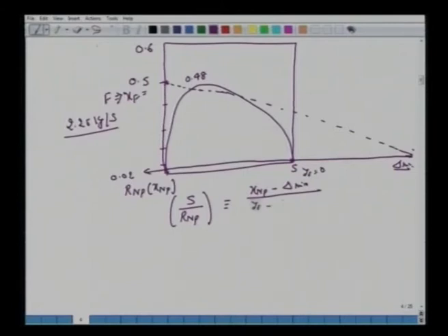That means we should make use of other quantities, let's say F here. Now if we take the tie line which passes through this and through this here, this will intersect at E1. Here we have extract and here we have raffinate. This tie line which goes through this, let's say we have Y1, which, if you notice, is 0.39.